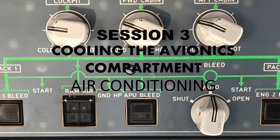Those close automatically in a closed circuit. Then there's the skin exchanger outlet bypass valve that opens, as well as the isolation valve. But what happens when the pilot pushes these buttons? Now I'm talking about the inlet bypass valve, not the outlet. The inlet bypass valve is going to open, because normally it would be closed. And so now it's open because of these switches giving those messages for that condition. Okay, so that's the closed circuit.